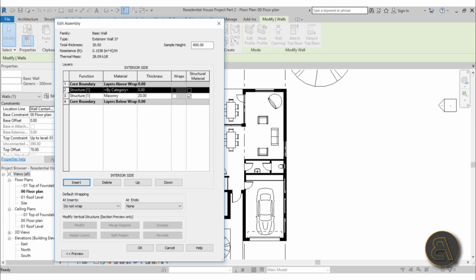We have another layer. Now in this case, this is not going to be a structural layer. We need to have some thermal insulation, and for that, let's create a thermal insulation wall layer. So let's just find here thermal or air layer. It can be either some sort of insulation, or it can be just an air layer, just a gap in the wall. So in this case, I'm going to use some insulation material, but first for the thickness, let's go with 15 centimeters. For example, in my country, that's like the minimum rule. That's what most people use. So let's go with that.